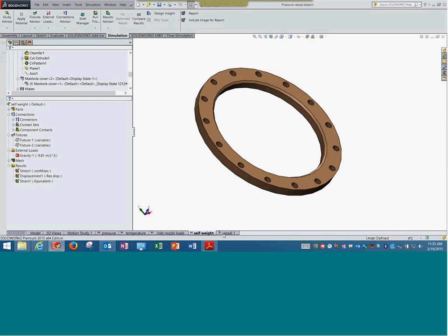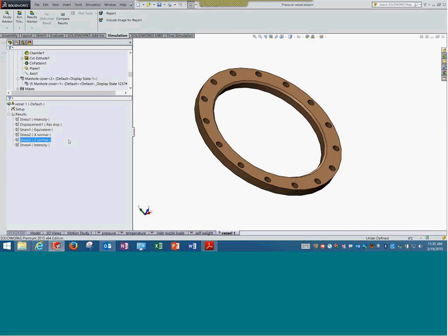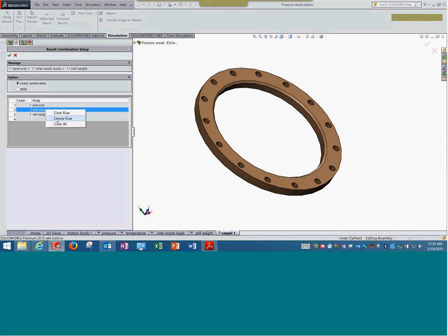To be quick, while we discuss this, one easy thing I can try is to reduce the number of studies that we want to combine here. Let me set up, get rid of this, linear combination, only one pressure. Will it at least solve this?